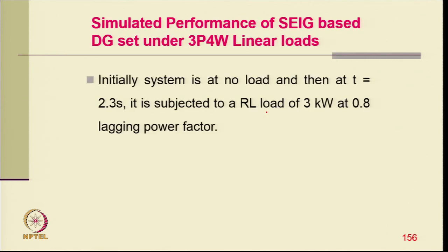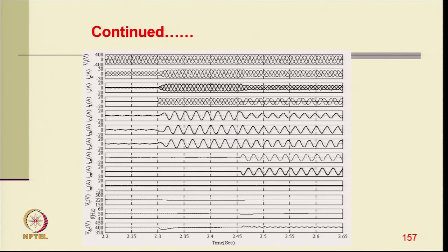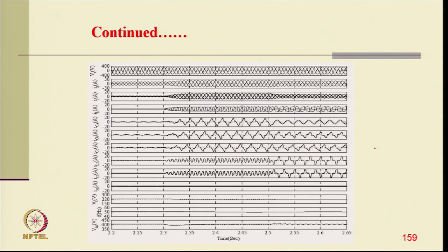These are typical data of the system, and then this is the dynamic performance. You can see the 3 phase load is fed at lagging power factor, then load unbalancing is introduced, but the generator current remains balanced and sinusoidal with the power compensation. This is of course a non-linear load, so it provides not only reactive power, but it also provides voltage regulation